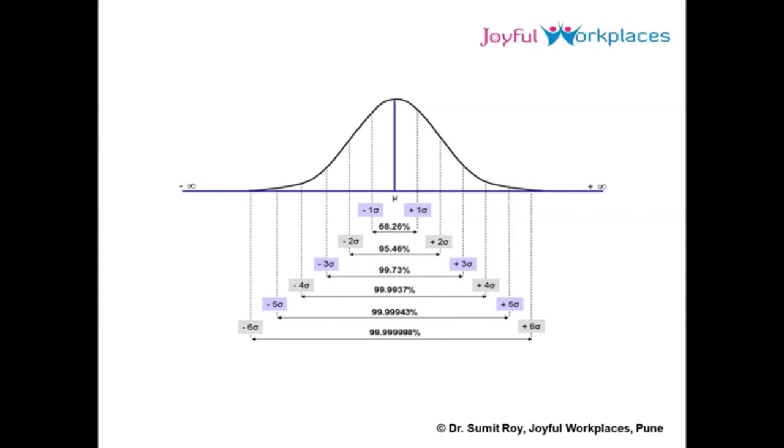The way your process is, that is how you are getting your upper control limit and lower control limit. All that you need to calculate them are the dimensions collected over a period of time in a certain way. And then when you calculate that, you get the sigma and the average. One calculator is good enough for you to calculate.